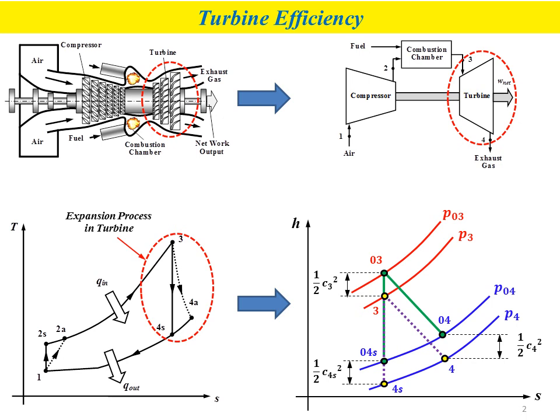However, because we already discussed the stagnation point, for turbomachinery we need to include the stagnation point and also the stagnation state. For the HS diagram, we need to include the stagnation pressure and also the static pressure at the inlet and the outlet of the turbine.